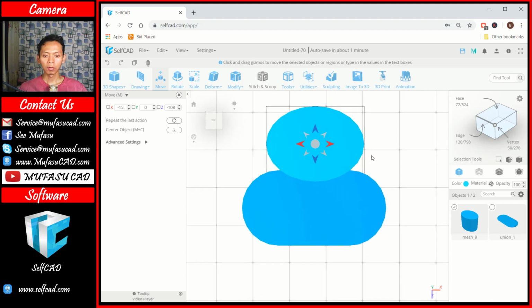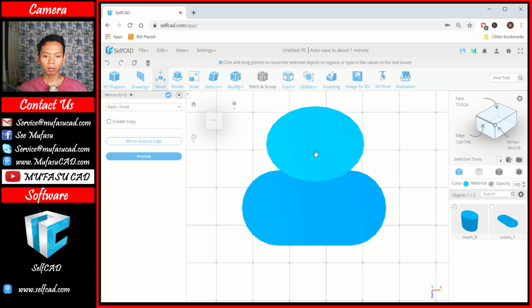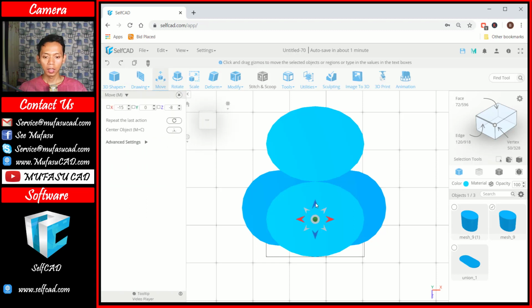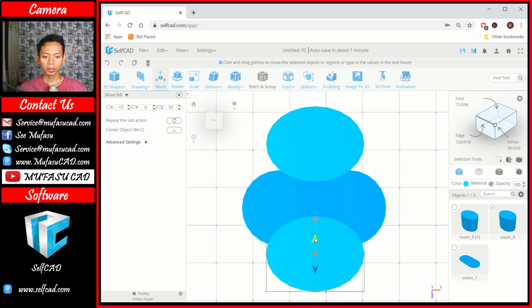We can use mirror tools to mirror these cylinder objects. You can click utilities and click mirror, and I will use create copy. Use front option, and you can click OK to apply. Now we can move this copy object. You can click move tools. In blue axis I will move into this point.